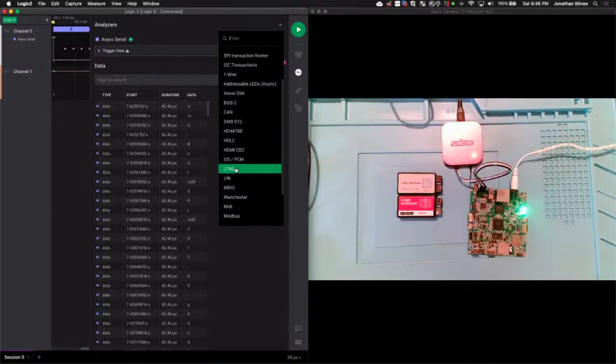Now, if you're wanting to program an MCU or upload to a flash memory, then you would need some type of programmer, and that's going to be vendor specific. Say, for instance, it's an STM32, you could use something like an ST-Link device. J-Link supports OpenOCD in a lot of cases, so it can support multiple manufacturers.